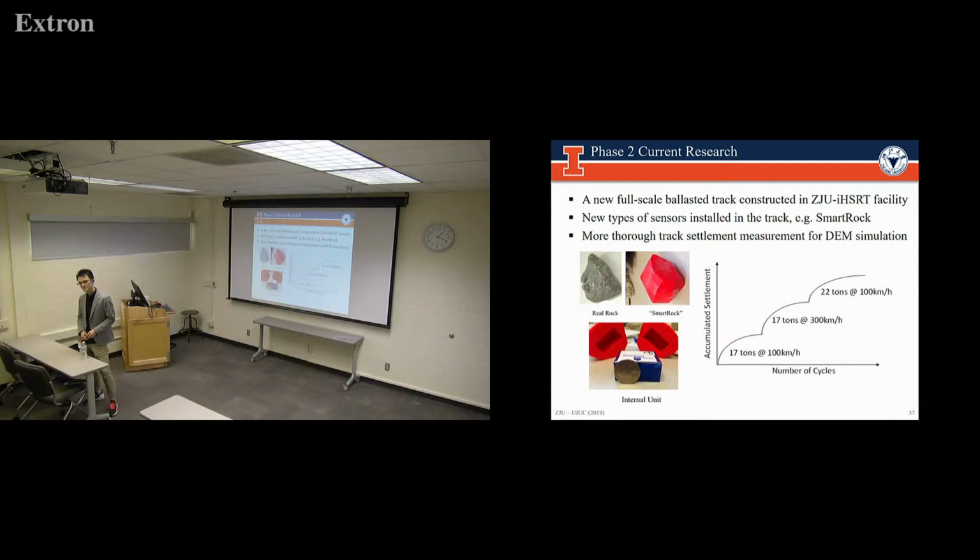Because at the end of the day, density is important, but I think stiffness or deflection is the one that represents the actual response of the layer. So you might do a sensitivity analysis, maybe not just air void, maybe also some sort of bonding between the aggregate. Yeah, this is actually applicable because we can do different gradations in DEM, and we already know their mass and their area. So I think the deflection can be a good representation. Right, and then we can get those from DEM and establish a database, and then we can do the calculations based on that database. Yeah, matching the gradation is not a problem.